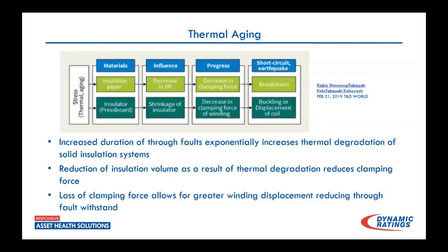So when the breaker's not operating or, let me rephrase that, is slow to operate, we're seeing a longer duration of fault current. So let's say we have a 3 cycle breaker that's out there, and that's 51 milliseconds that we get to clear that. But you've got to remember, we do have this 15 cycle delay in between those. So, roughly, I'd have to do the math. Roughly, so quite a bit of time longer that fault's in. So let's just say that distribution breaker is 2 cycles slow or 4 cycles slow.